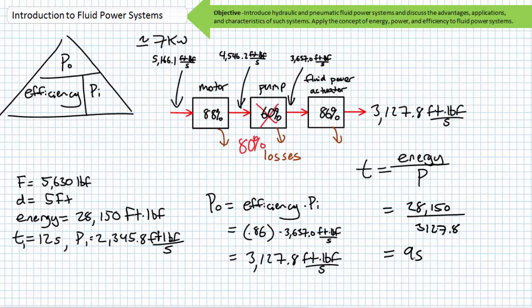In conclusion, this lecture took a brief look at fluid power systems. We defined fluid power systems and identified critical fluid power properties, pressure, flow rate, and valve position, and discussed how these properties must be controlled and measured by a fluid power system to control the strength, speed, and direction of the resultant mechanical output. We introduced a couple basic fluid power devices, discussed their general purpose, and drew their associated schematics.